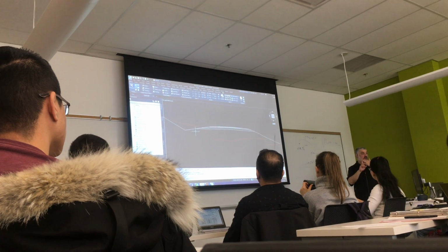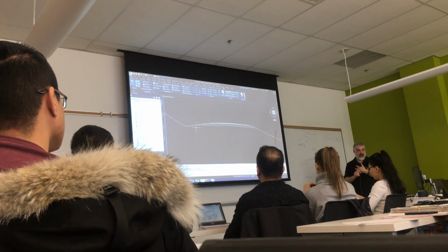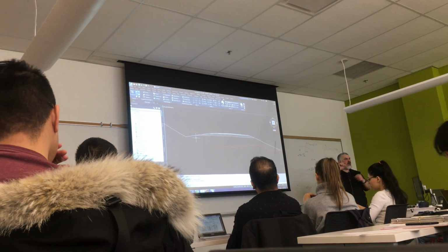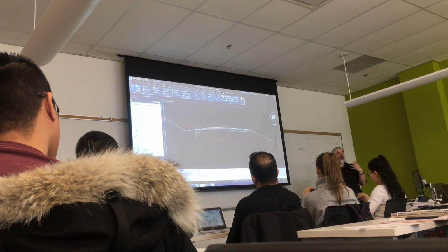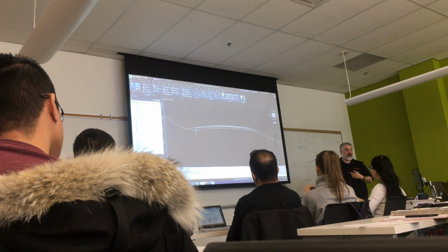You need to know the slope of the pavement, the main lane of the road, 2%. You need to know the slope of the shoulder. You need to know the slope of the subgrade. You need to know the pavement thickness. All the numbers, whether it be a depth, a width, or a slope, are required to draw this. Everybody agree? Without those numbers, I can't draw this.